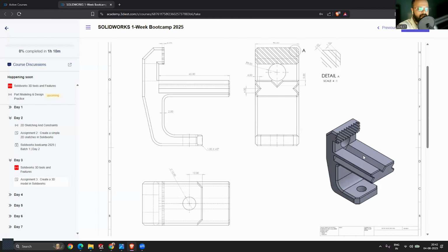But now we'll select this plane as a sketch plane. So the moment I move my cursor onto this plane, you can see it is getting highlighted, right, like this. So I will click on this plane, and now that plane is ready to start creating a sketch. So now that plane is acting as a sketch plane, and that's why you can see all the sketch tools are active. So here we are going to create 3 rectangles, right?